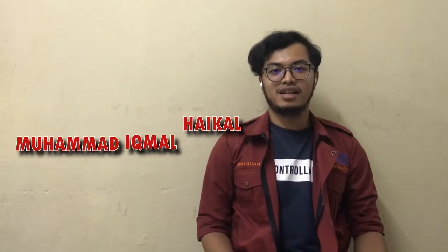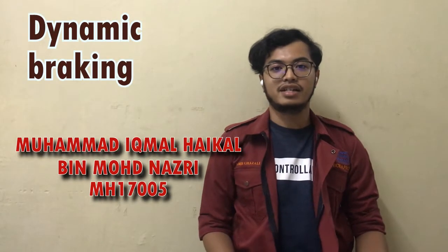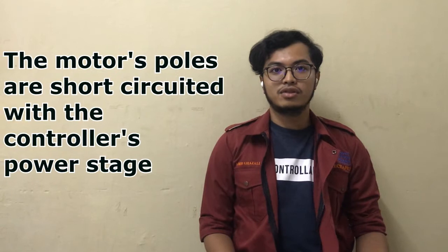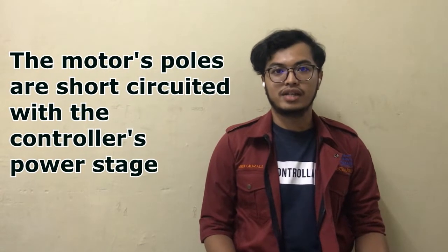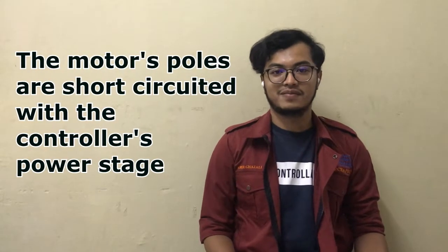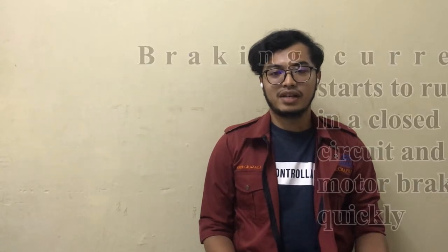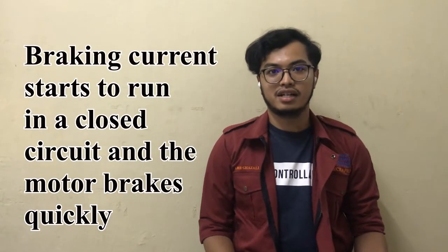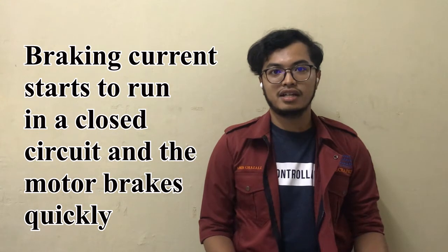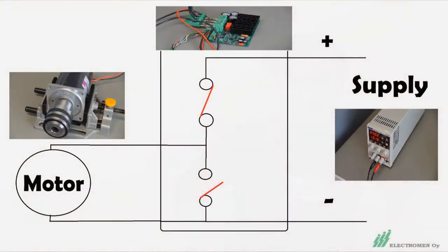In this video, I will explain dynamic braking. The motor is short-circuited with the controller's power stage. Braking current starts to run in a closed circuit and the motor brakes quickly. This figure is meant to demonstrate the basics of dynamic braking.